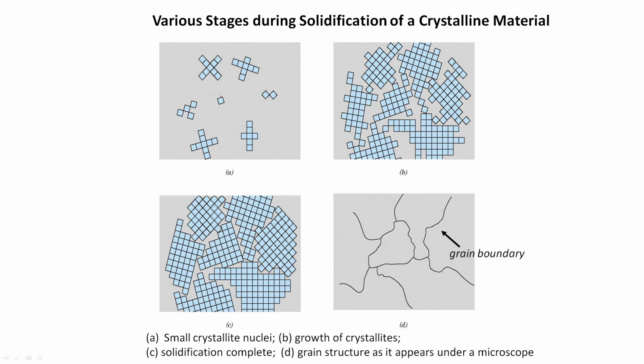In the liquid everything is haphazard, because there is no crystalline structure in the liquid. But nucleation is a fluctuation process, or stochastic process. In some part of the liquid, these atoms will align in a regular, ordered manner. That is what is called a nucleus.